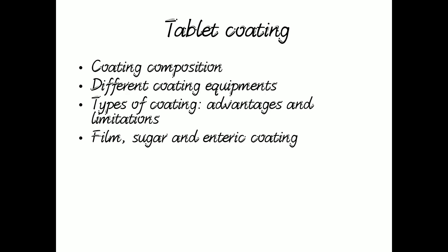Actually, once you are applying the coating solution, if it is not adequately spread before the drying, this may lead to orange peel or bumpy orange effect. That means the spreading is either done by too rapid drying, or the solution was having very high viscosity. So if you dilute the solution with additional solvent, that may be the solution of this problem. So this is the orange peel effect, which is the most important one and asked in the GPAT exam.